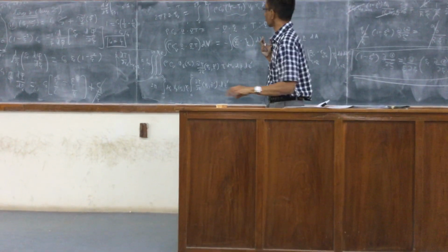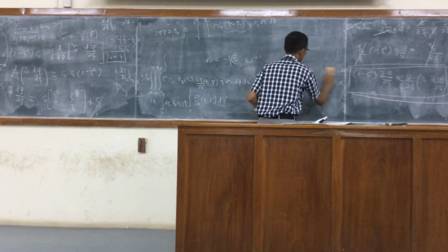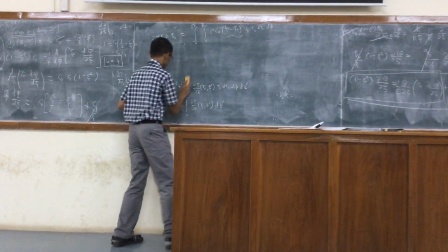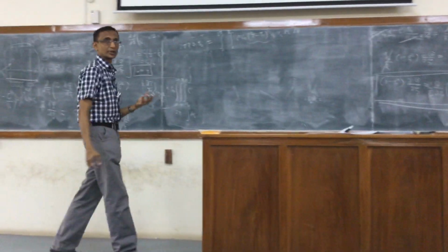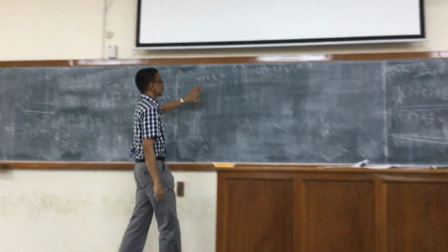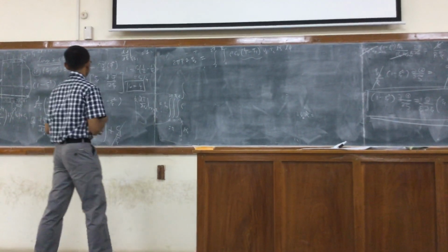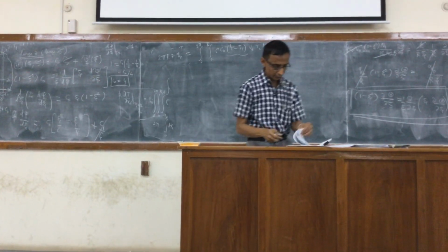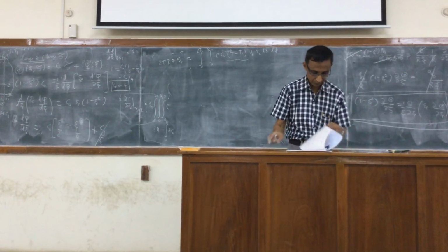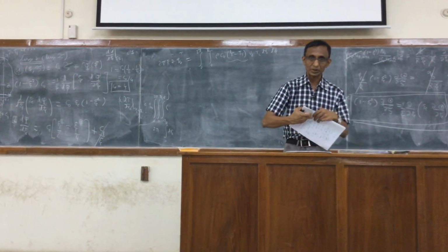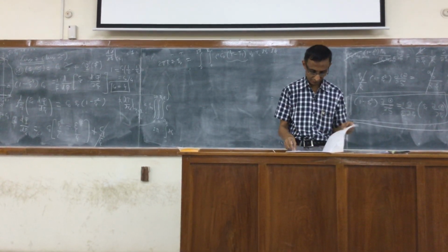Now, having justified it, of course this means that the internal dissipation effects are neglected, otherwise you get a more complicated equation that involves a Brinkman number. Right? So this is for the special case. So now you can easily convert back, and maybe I'll just write out the result because we're running out of time. You can go ahead and write it in terms of the dimensionless temperature and the dimensionless